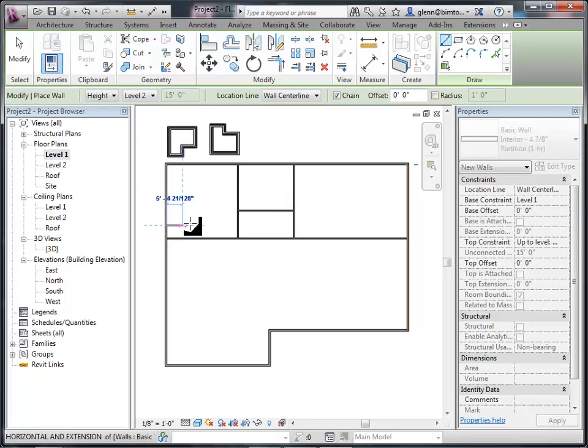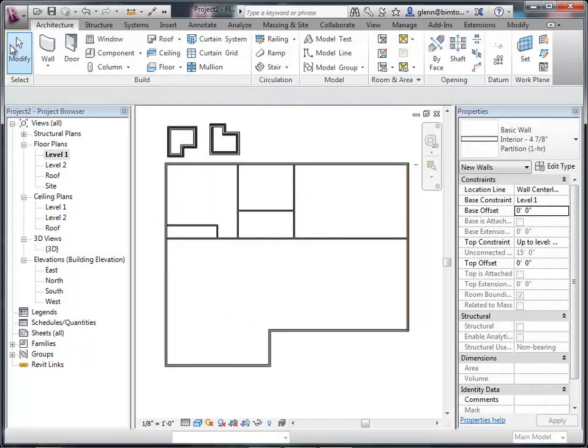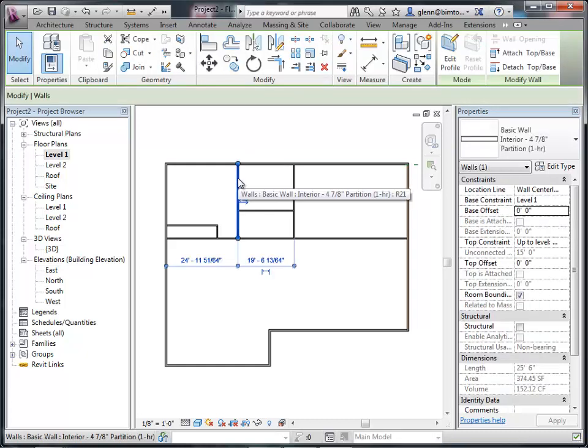This room over here is going to have some sort of closet across here. My scale's way off, so don't hate me for my scale, but it's really pretty bad right now. But go ahead and start placing the interior walls, the exterior walls. Just do something in terms of getting the basic layout. Again, as you're working, if it turns out that after you place the walls, the dimensions aren't quite right, you want that to be 20 feet as opposed to 24 feet, you could always go through and move things after the fact.